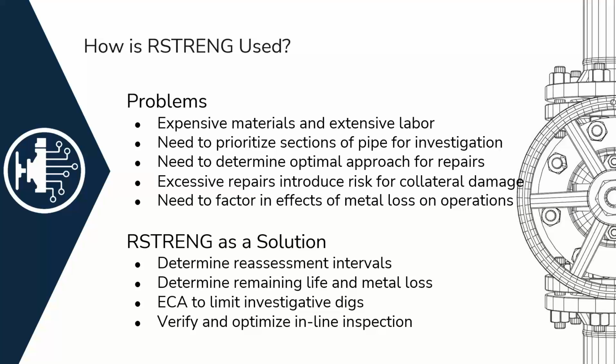And is there any cracking associated with the metal loss? These are really important components to notice. The pigging companies can't always tell you that there's cracking associated with corrosion, and there is, and this is why we need people that understand metal loss defects and how they're associated with other damage on the pipe, because it just doesn't happen all by itself.